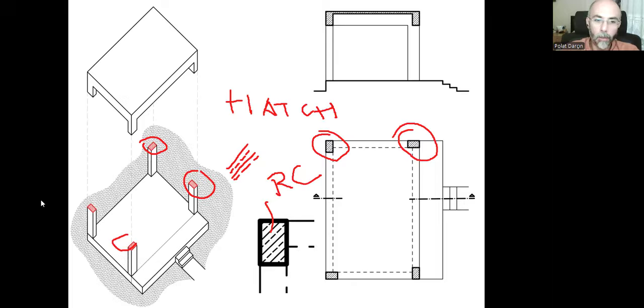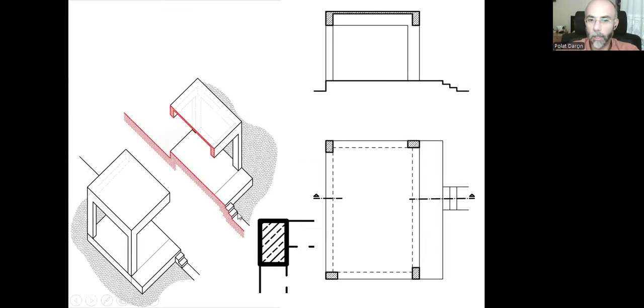And I need to do the same for the section as well, because all these cut surfaces of the beam and the floor slab and the other beam are going to be reinforced concrete. So I need to fill the whole gap with this same hatch. And I can add these inclined lines, but this time only just inclined lines like this.